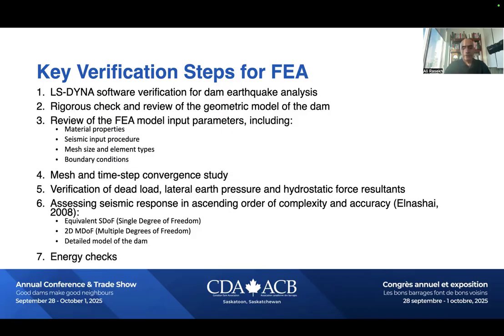Rigorous check and review of the geometric model, review of the different aspects of the FEA model, such as materials, seismic input. Very, very important is the seismic input, because it's sometimes given to us structural engineers like a black box, and I have been in scenarios where it has been troublesome, like we have received the wrong seismic input, which has caused miscalculation and miscommunication and misconclusion.